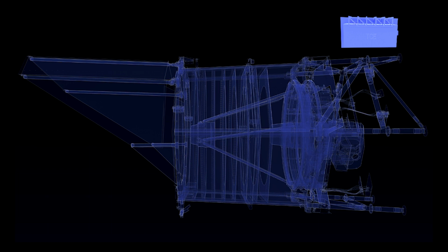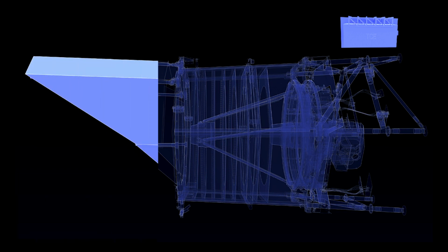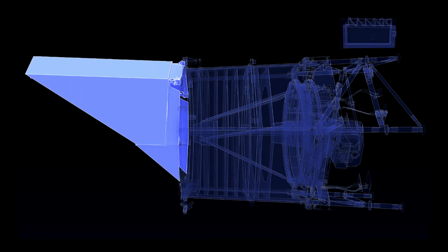The telescope control electronics, TCE, is the brain of the telescope. It is designed to provide thermal control using hundreds of heaters and sensors. The TCE will also control the secondary mirror's position with 6 alignment drives and 2 focus drives, and the AOM with 5 actuators. The deployable aperture cover, DAC, is responsible for keeping light out of the telescope barrel.